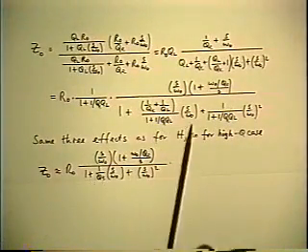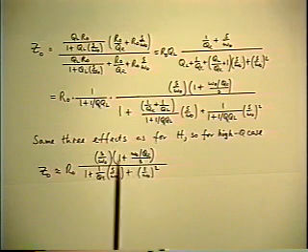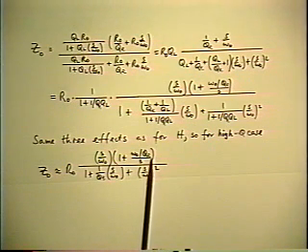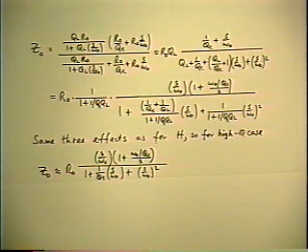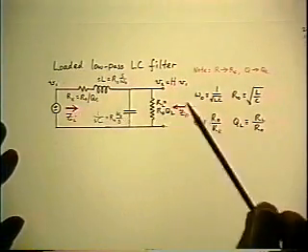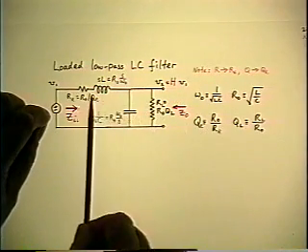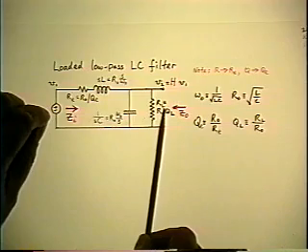So the quadratic goes back to the simpler form. Leading coefficient goes to the R0. This time there is no additional corner frequency resulting from the loading. That is also consistent with what you would expect just from looking at the circuit. The output impedance is found by making V1 0, so you have the parallel combination of three branches.